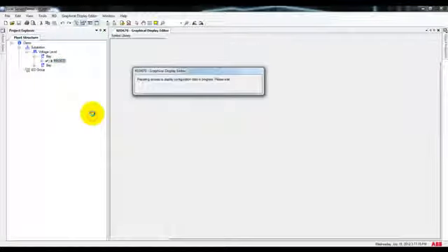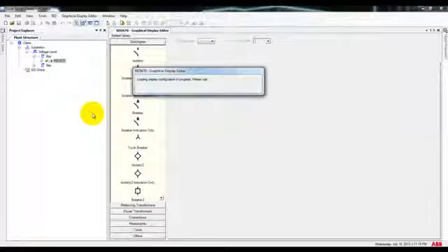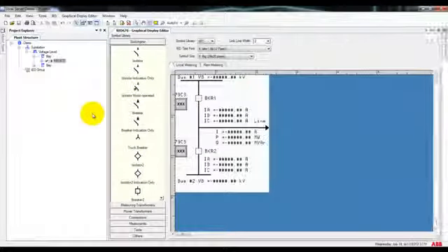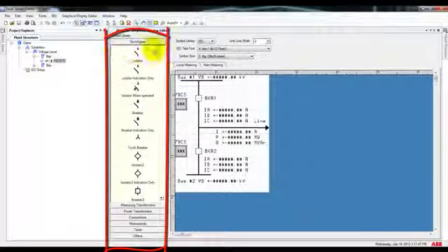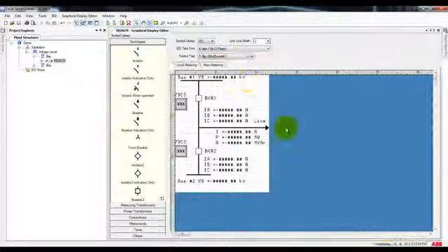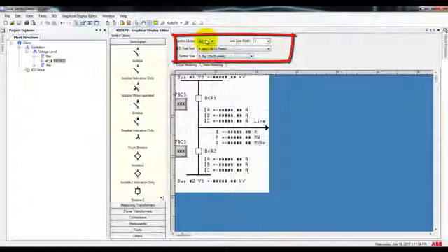The Graphical Display Editor tool is used to represent a single-line diagram of the system that your relay is protecting, create an interface for the control part, monitor the voltage and current, and calculate values such as sequence components and power. Once the Graphical Display Editor tab has opened, you'll observe that you have a symbol library, a display window with your display pages, and drop-down menus to edit your symbols.